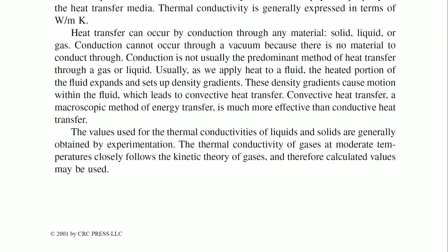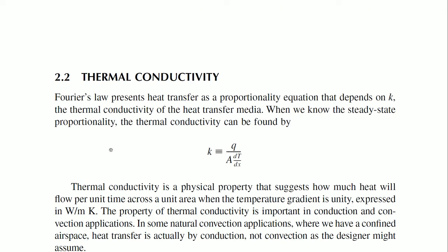As in this here, most important, this is what I wanted to tell you, the issue is about experimentation. Without experimentation, or trying to establish the actual conductivity coefficients in actual use, trying to extrapolate may not be that effective or useful, because even surface characteristics, the way things are mounted and the way things are oriented, all of them seem to make a tremendous amount of impact.